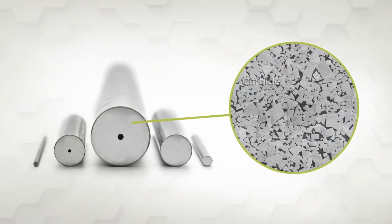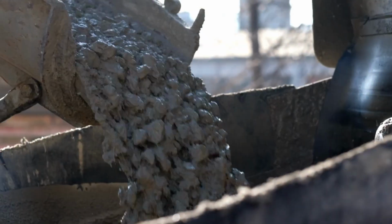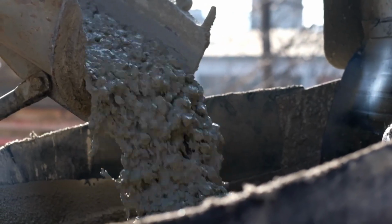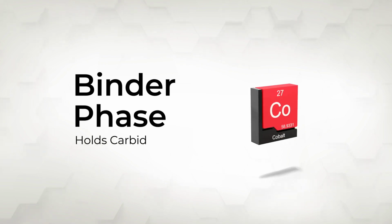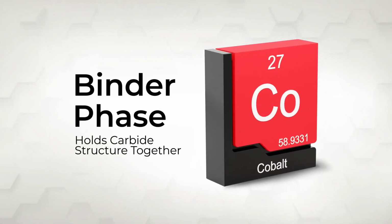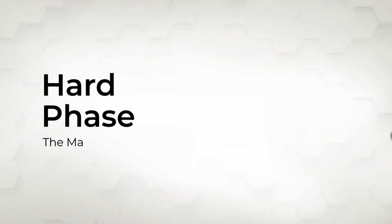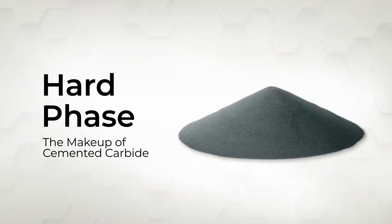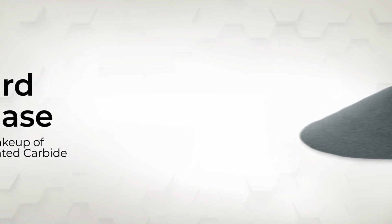Cemented carbides are a range of composite materials that consist of hard carbide particles bonded together by a metallic binder, conceptually similar to the way that gravel aggregated with cement binder makes concrete. For cemented carbides, the binder phase that holds the structure together is most often cobalt. There can be one or more hard phases. Primary among these is tungsten carbide, though there are others like tantalum carbide, titanium carbide, or niobium carbide.